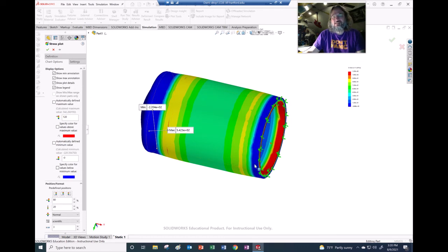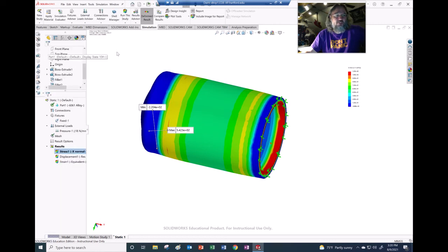But you'll notice that the colors have changed rapidly right along where we attach the thing, right? There's actually a number of reasons. One of them is that we're also constraining it from getting larger right there, so that's going to be a defect in what we're looking at. So when we go to actually figure out what the values are, we want to pick some place that's far away from where the boundary conditions are applied, if we're going to try to understand what we're looking at.